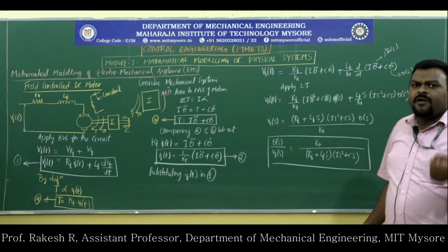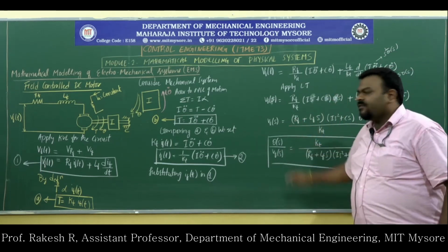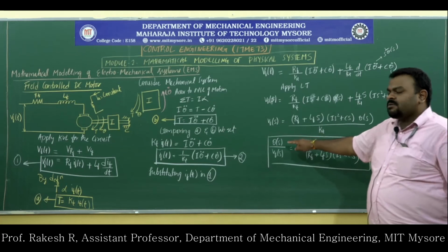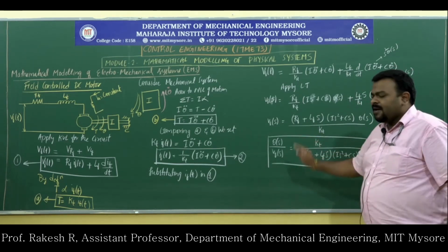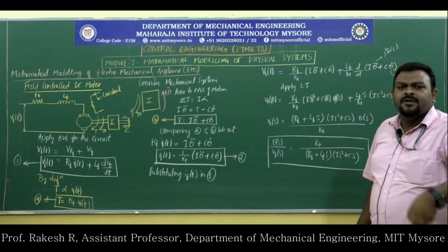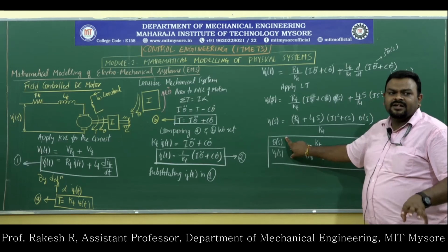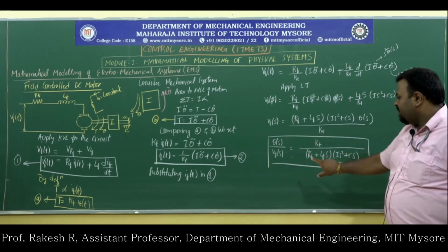The definition of transfer function is the Laplace transformation of the output variable to the Laplace transformation of the input variable. The Laplace transformation of the output variable is rotation. It is a mechanical system. The Laplace transformation of the input variable is voltage. It is an electrical system. Hence, it is called an electromechanical system. So, we have got a transfer function theta of S by Vf of S.